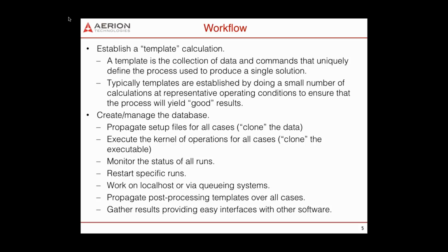And that vetting process to establish the template is kind of iterative. One goes back and forth looking at the quality of the solution, changing mesh resolution or flux functions and limiters, until finally the user is happy with the results at the representative conditions. And then one basically clones that template over all the other operating conditions requested by the database. And that process, which is the creation and management of the database, is where Hydra comes in.